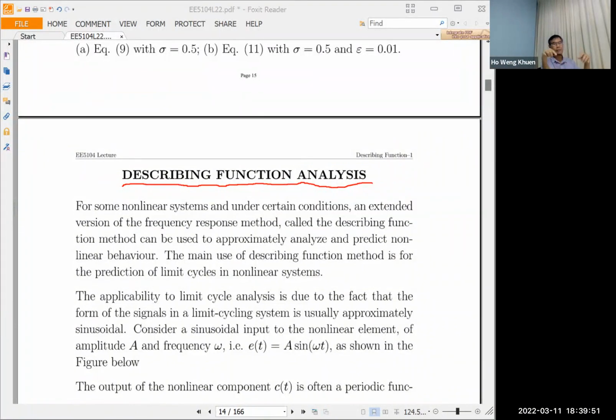Beyond 20 kilohertz, your amplifier is beyond what we can hear. So your 3 dB point must be within 20 kilohertz. Outside that, you can roll off the gain.